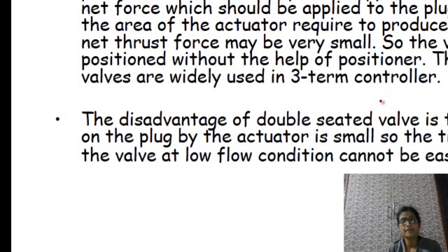That means a leakage flow will exist for a double-seated plug. Whereas for a single-seated valve, the major advantage is it can fit the valve more tightly. That means it can close the valve more tightly than a double-seated valve.